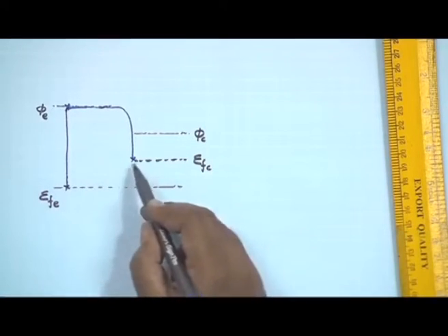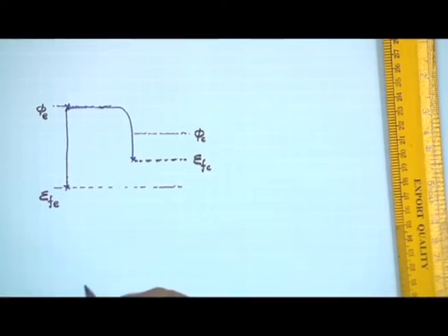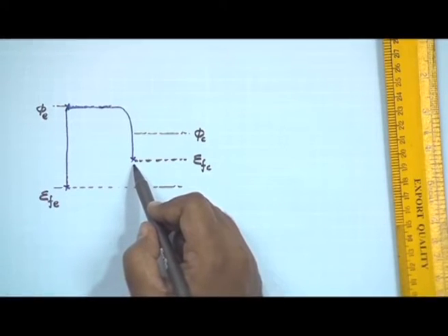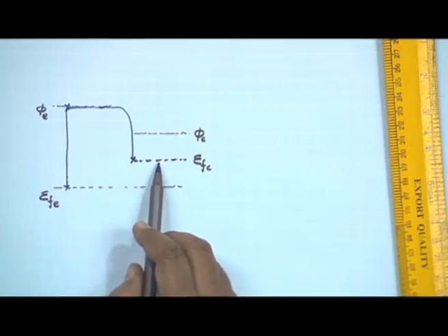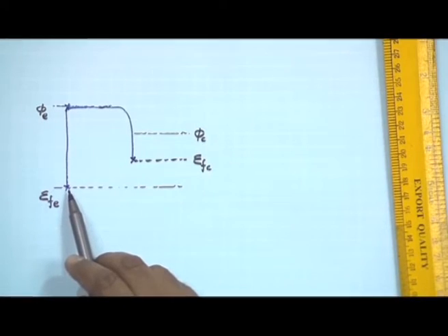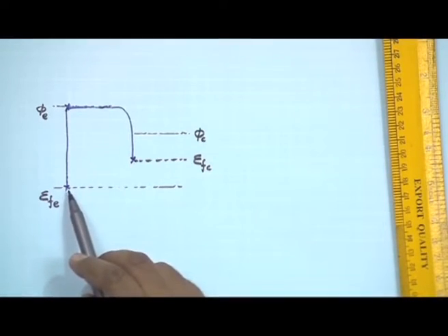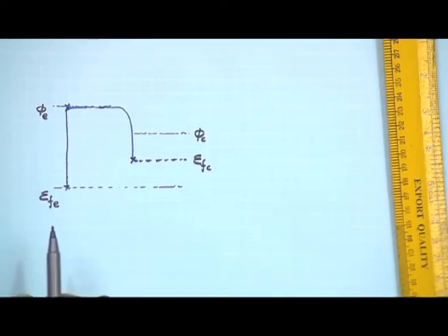But remember, this is higher than that of the emitter surface. So, if I attach these two points externally, then the electrons will tend to move from the Fermi level of the collector to the Fermi level of the emitter, which is at a lower energy level, if we collect it through an external load. Okay. So, this is how the thermionic generator works.